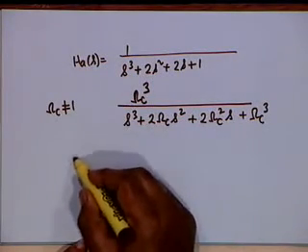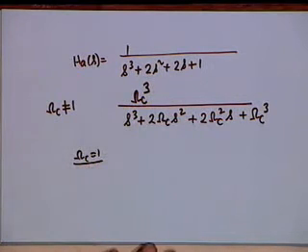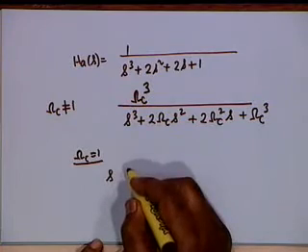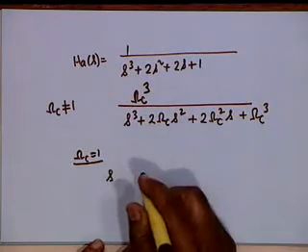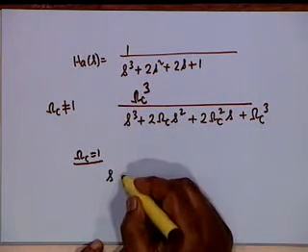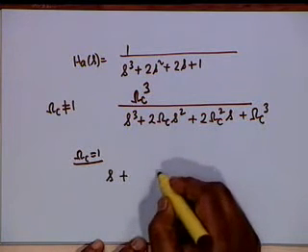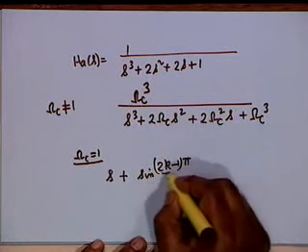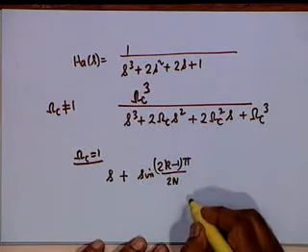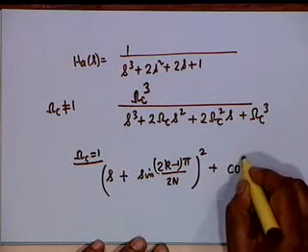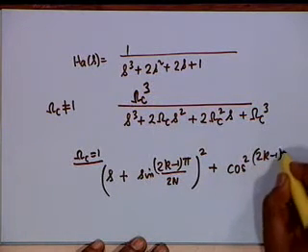complex conjugate, and let us say for simplicity omega c is equal to 1, then two complex poles shall give rise to a quadratic, right, what we did in the third order case. The quadratic polynomial would be S plus sine of 2k minus 1 pi divided by 2n, that is the real part, whole squared plus cosine squared 2k minus 1 pi divided by 2n.